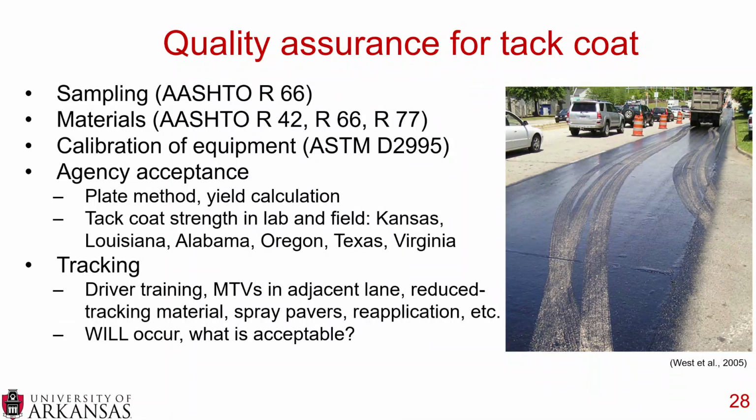This is a very famous picture from Dr. Randy West at NCAT. This is exactly what you do not want to see, which is a beautiful tack coat that is placed and that is being picked up and carried away by that truck sitting there that probably has asphalt mixtures in it and the paver is just to our left. But that is an area where the pavement will not properly glue to the existing road, and it's right in the wheel path, so you're probably going to have problems down the road.